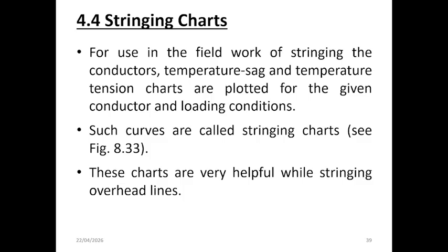To assist with this process, you must prepare the graphical relationship between temperature and both sag and tension for a specific conductor under defined loading conditions.